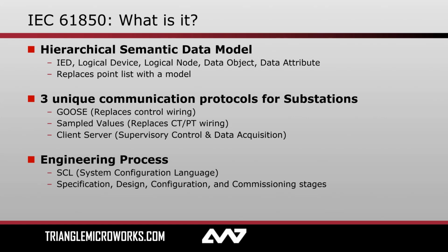It's not one communication protocol, but it's really 3, used for different functions or applications within the substation. GOOSE to replace the control wiring flowing back and forth between our different pieces of secondary equipment, different IEDs.